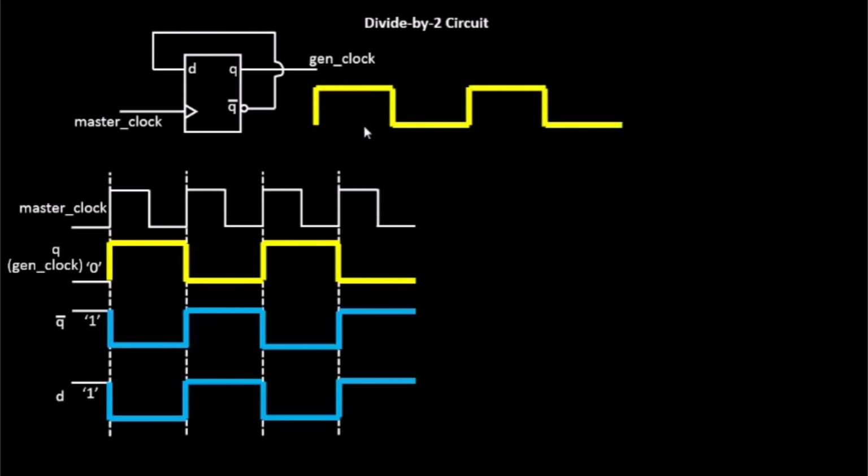over here. So this waveform that you get at this particular point of time, the further circuits which will be connected to this particular gen clock, which are these flops, have to be characterized with this waveform and not this waveform. This is the waveform which is being fed from the external world. So we create this as a master clock, and the output of this clock, which is the generated clock, we create separately because this is a static timing analysis tool.